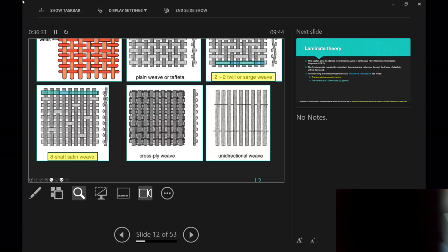Yeah, that's absolutely fine. Bear in mind, when it comes to composites, the problem mostly lies where you've got double curvature. If you've got single curvature, you're fine. If your single curvature is not too curved, you're fine. In the case of an aircraft, because of the aerodynamic requirements, it's not too curved. It's slightly, probably less than that.